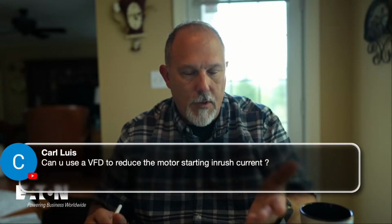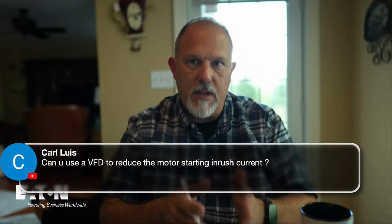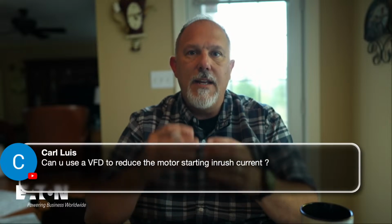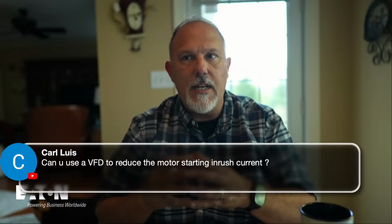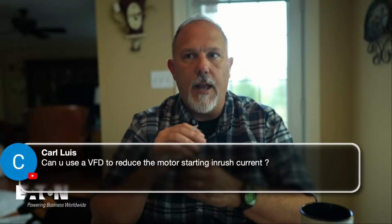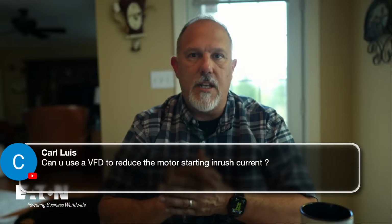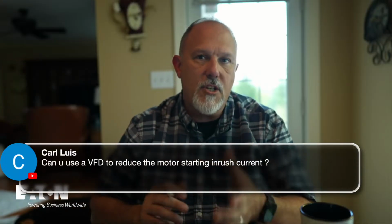And Carl, to your point, we're going to throw a VFD in here and look at VFD requirements. Yes, the variable frequency drive takes care of ramping up the motor. The VFD isolates you from the activities in that motor and the requirements from inrush currents, because it will ramp the motor up, ramp it down, start it, stop it.